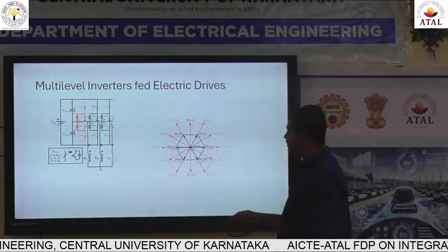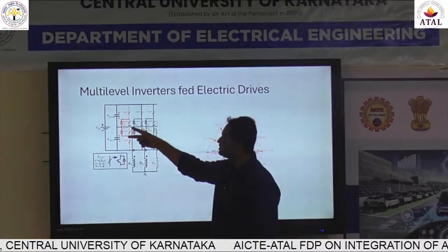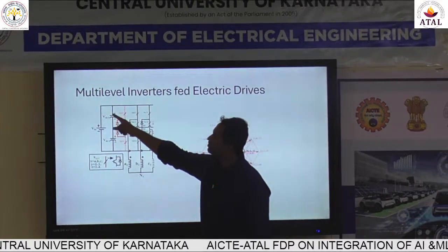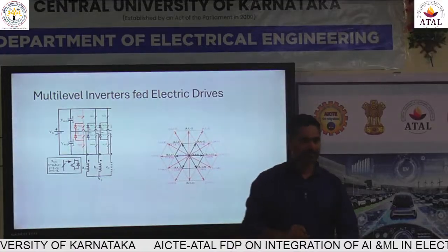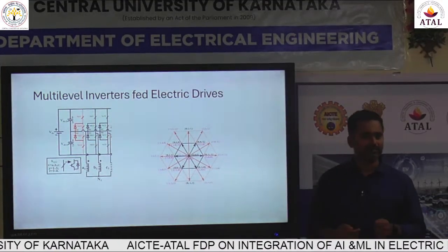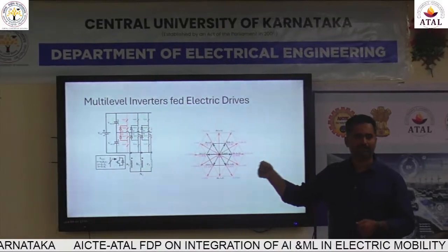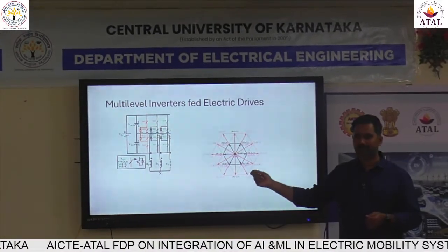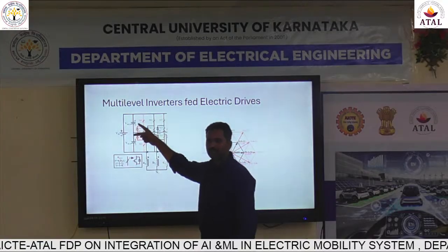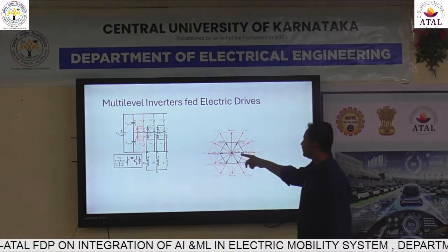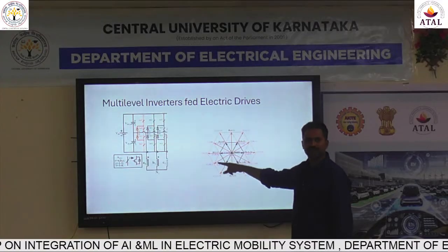But if you look at the 3-level, if one of the legs fails, you connect it to 0 anyhow. These capacitors were designed to take care of the neutral currents. Those capacitor midpoints, that's what we have done tons and tons of papers on, saying NPC, neutral point fluctuations and all of them. So these 2 capacitors were ready to take it, and if you look at the space vector, you already have the 0 vector and all the redundant states sitting here.